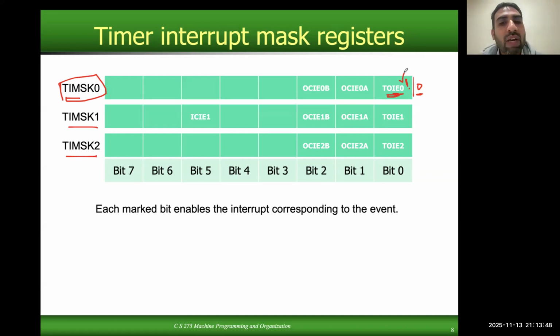And when the value of the timer register became equal to the output compare register, a flag was set, the output compare flag. For both comparator A and comparator B, there were two different flags. So if you want to use polling, by default all of these bits are 0, and you continuously check the flag, as we have done in the examples in the previous lecture.